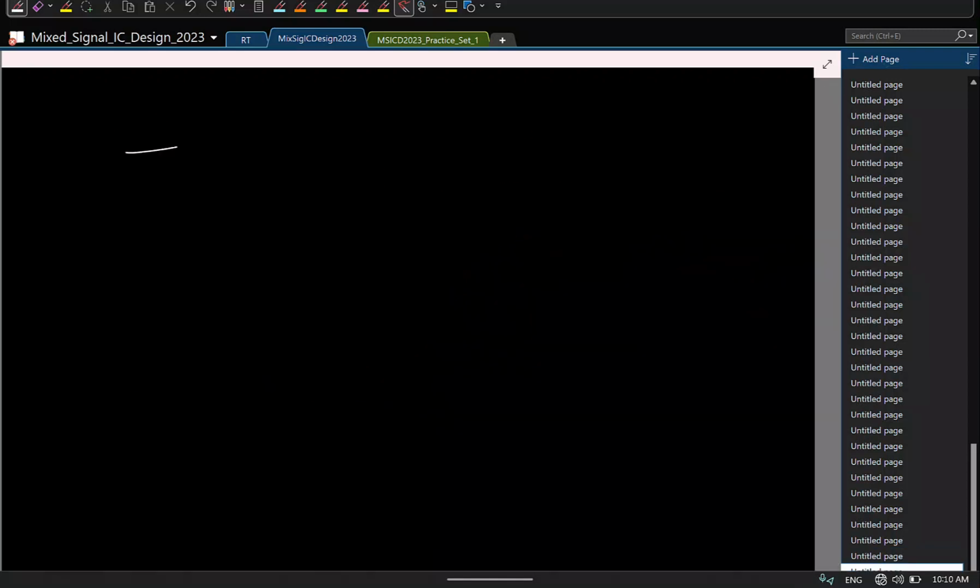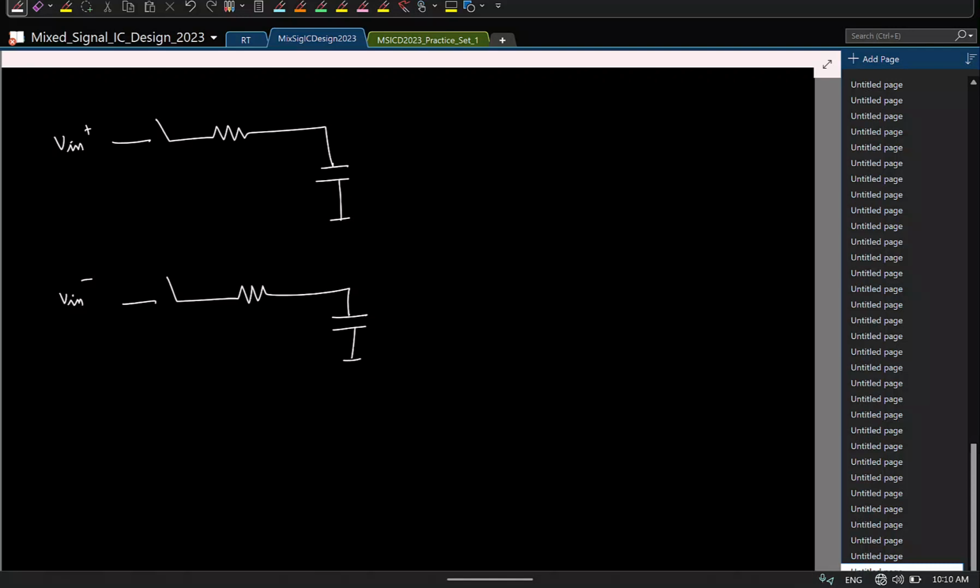You'll be sampling the signal, and in practice we have differential signals. So let us say this is sampling the positive guy and this is sampling the negative guy. So we'll have two sampling networks like this. And let us say this is VO, I'll also call it VO plus and VO minus. So VO plus of n will be Vn plus of n plus some, let us say, Vn1 of n. This is the noise. So this will be Vn minus of n.